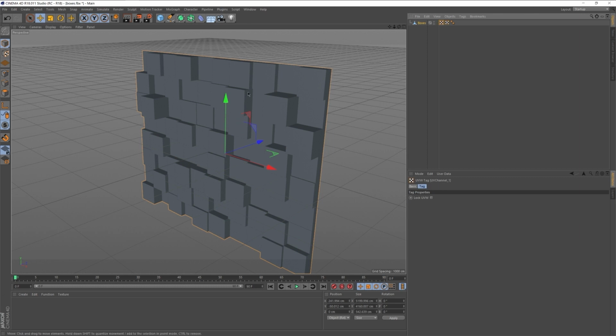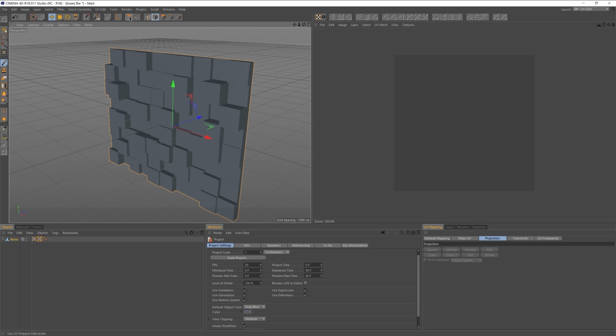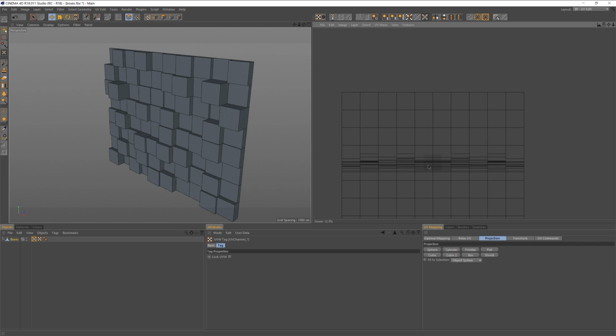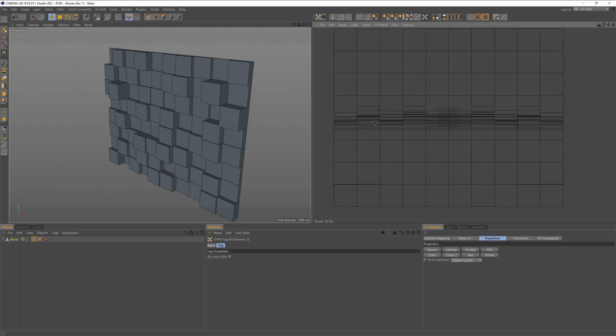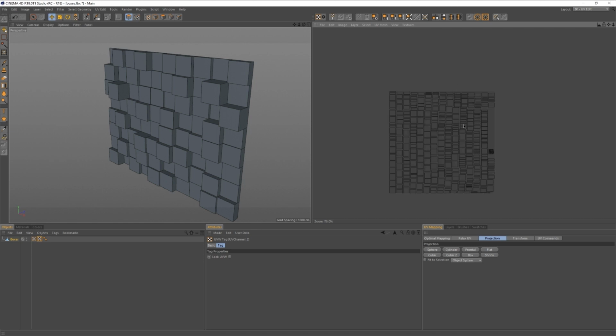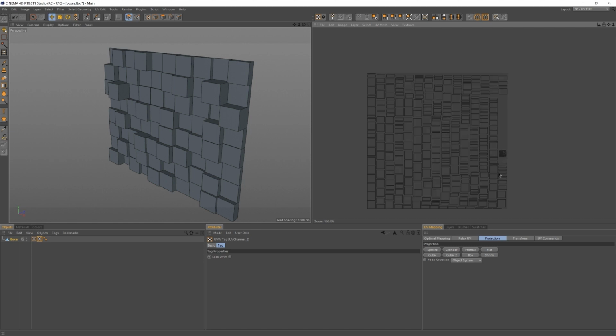As mentioned, one is tiled and overlapping, and one is unique that is being used for the bake lighting. Let's preview that in the UV editor. Right, so this is our first one. Let's pan out. Yep, definitely overlapping, definitely not unique. And here's the second one. And I can see every single facet laid out in available UV space very, very neatly.